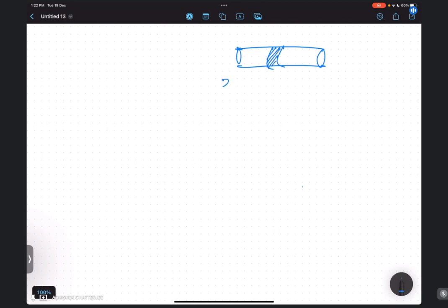ठीक है, अब ये तुम्हारा Z इज इक्वल टू 0 है, यहाँ पे कंसंट्रेशन CaS है, ये Z इज इक्वल टू L. Okay, let the radius of this be capital R and the diameter be D. What we say is that let us take a small strip. This strip starts at Z, and it is of a thickness of dz. So when this reactant is entering, it will enter at Z, and when it will be exiting, it will be exiting at Z plus dz.